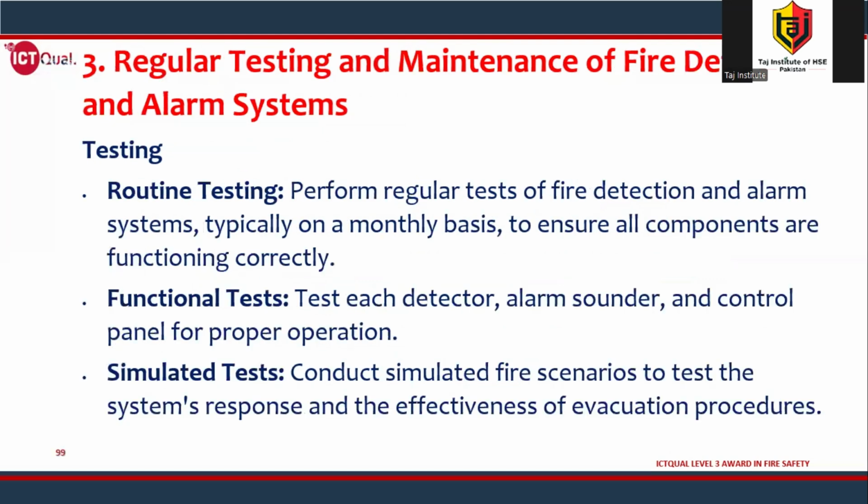Testing. Routine testing. Perform regular tests of fire detection and alarm systems, typically on a monthly basis, to ensure all components are functioning correctly. Functional tests. Test each detector, alarm sounder, and control panel for proper operation. So you have to test each device. All devices should be in proper working condition.